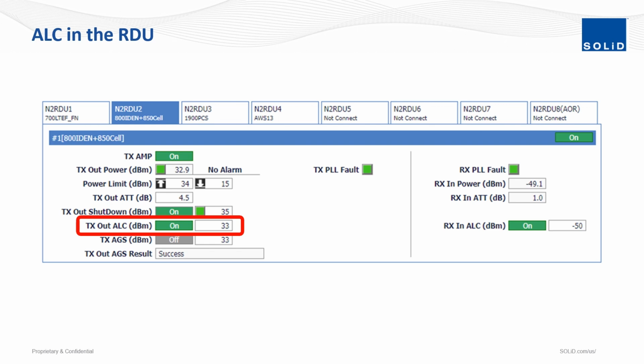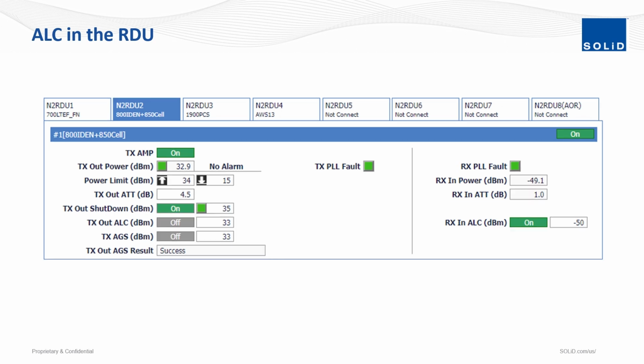An Alliance DAS remote should not always be at maximum power with ALC values fluctuating. In that scenario, the reference signal power and thus the coverage area would also be fluctuating. Let's talk about the RX-in ALC.